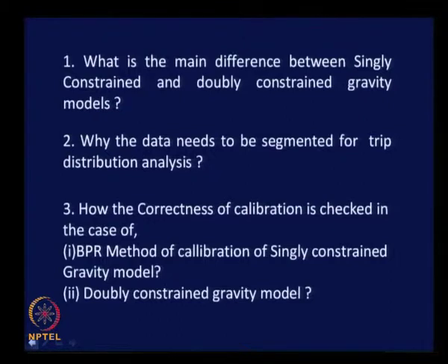What do you get? What form of result you get when you use doubly constrained gravity model for trip distribution? Would you be getting trip length frequency distribution curve or something else? We will be getting a matrix giving trip interchange information between zonal pairs at the end of distribution of trips using doubly constrained gravity model. You will simply get a matrix,